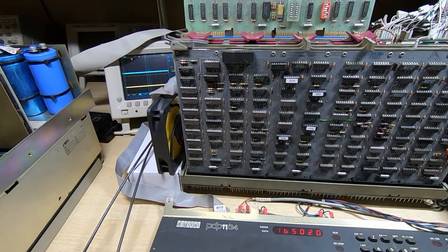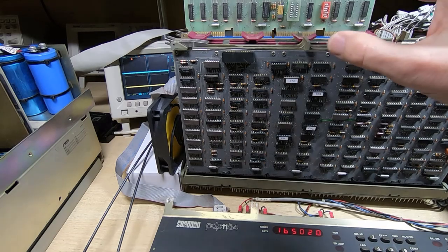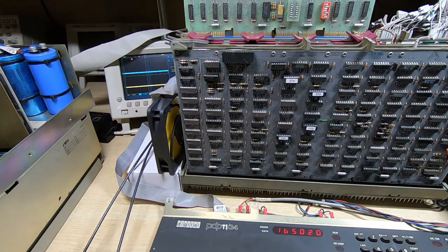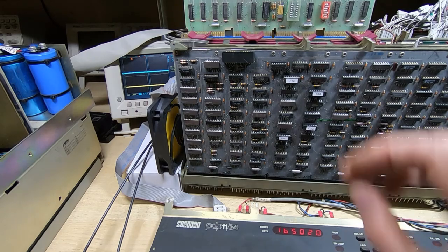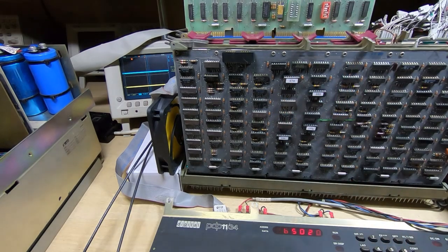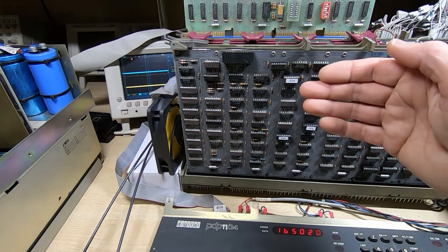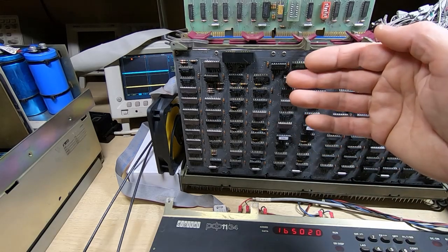So when you do a full reset, the RX211 should be in its default state, and you then supply it with commands and data, and it will step through the state machine to provide the various functions that are required for the interface. But at each step it requires specific information. You access the RX211 through two addresses. So this one's currently mapped to 777170 and 777172. The first of those addresses is the control and status register.